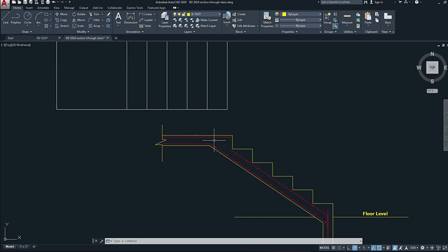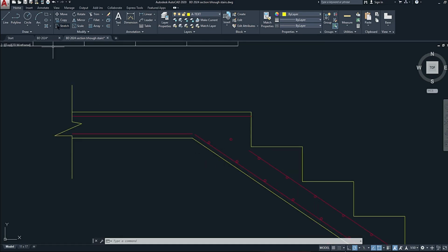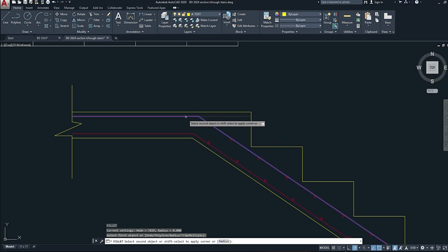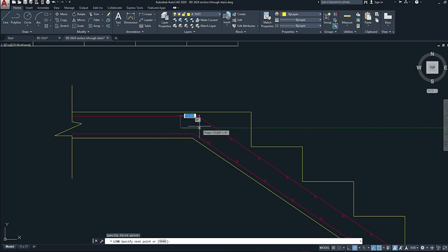Again, there is some more conflicts when it relates to reinforcing this area here, but I'm going to teach you my expert opinion in relation to this here. Some persons would think that you should join these like this, all right, and then that would be it. While some say no, that's crap, because what happens when the stairs comes under pressure, what happens is that it will crack along here, and this half will fall down and this half here will be somewhere else.